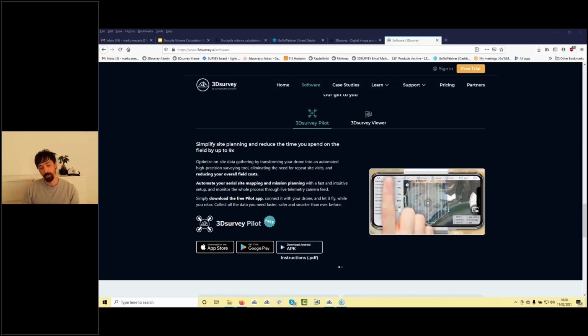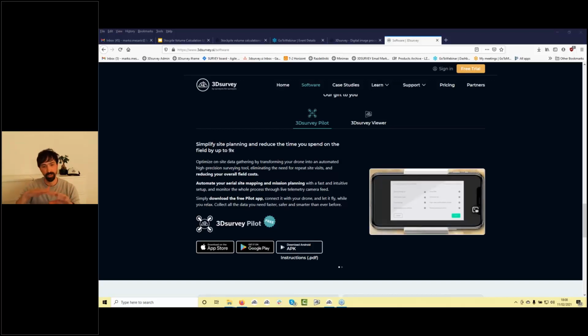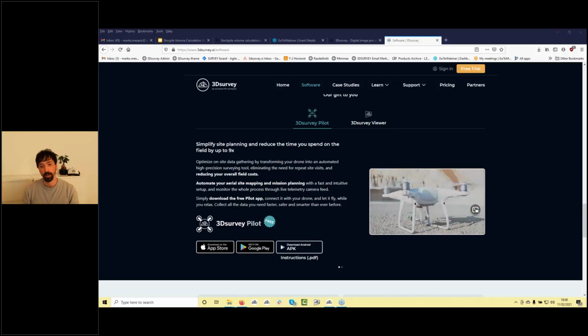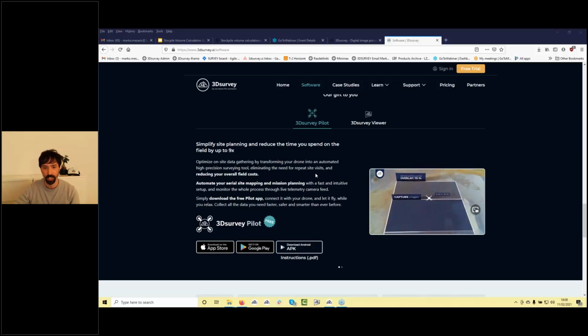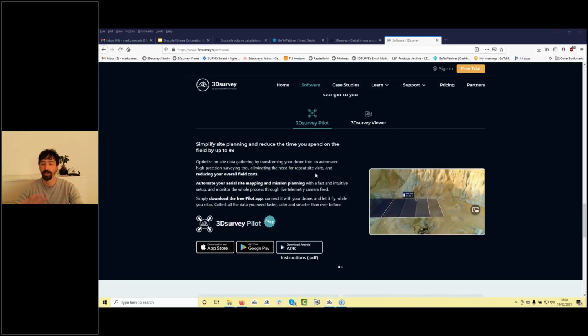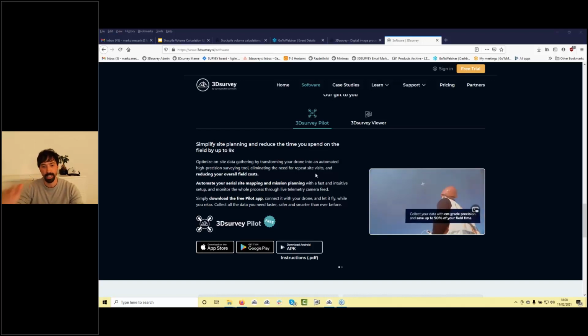So even when we use just a single GCP point in addition, we improve this displacement. Horizontal position is always perfect, but for height we advise still to use at least 1 to 4 ground control points per project. So I would advise you RTK if you have a lot of projects. If you're doing this stuff once per month or once per 2 months, then take the Phantom 4 Pro.